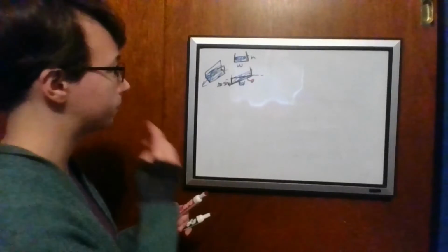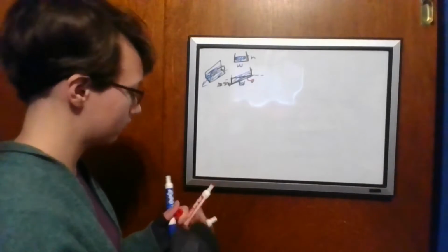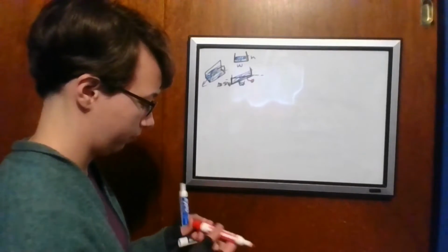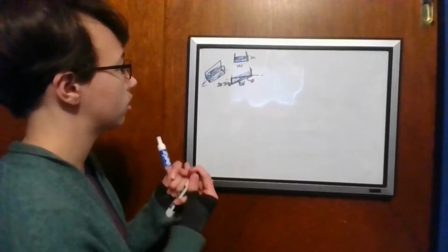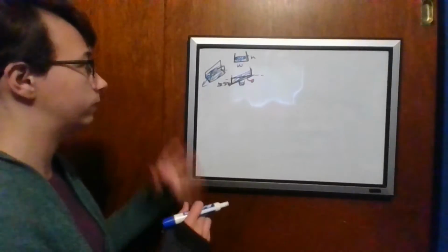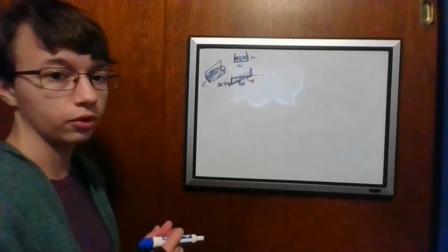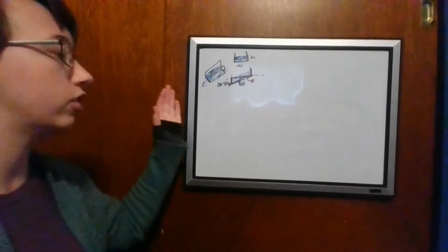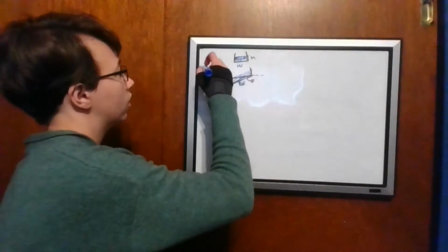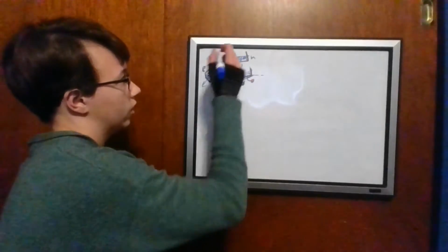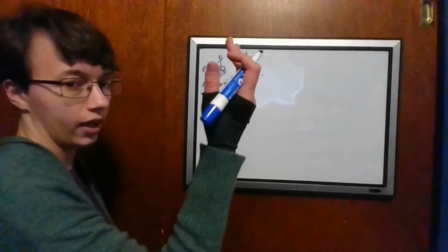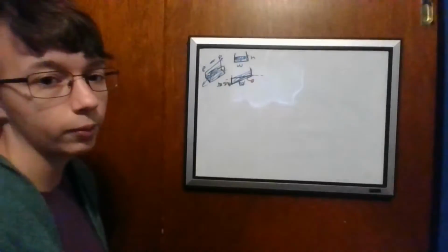Alright, so next we can start to plug this into Bernoulli's equation. So this is a gravity-driven flow because both the pressure at point 1 here and point 2 here are open to the atmosphere, so those pressures are equivalent, so there's not going to be a pressure difference.